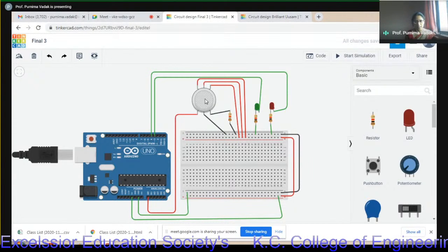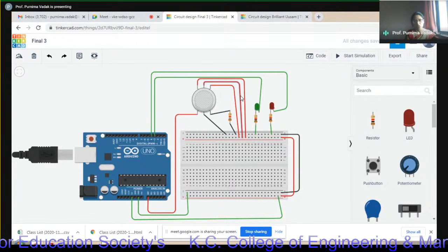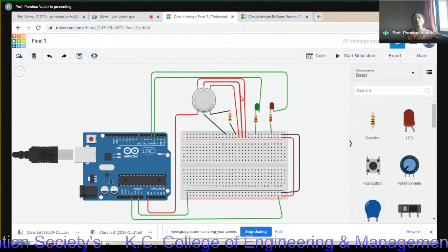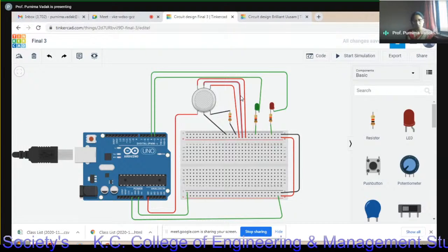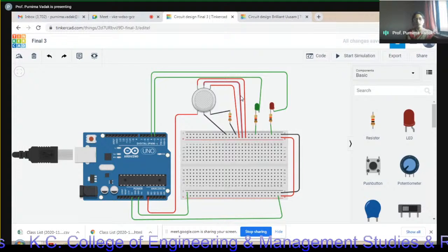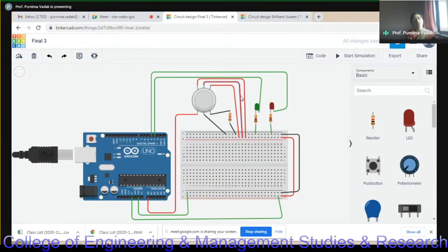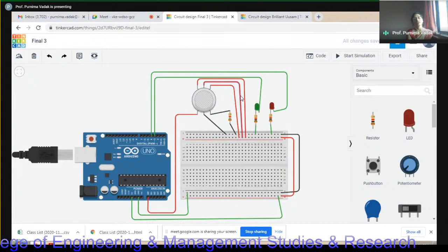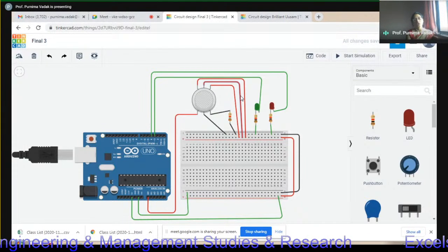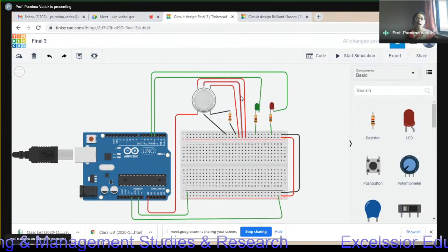Now, what is this gas sensor exactly? There are various sensors used for detection of gas. There are different sensors for different gases. Here, this sensor is used for detecting the LPG gas present nearby. What happens whenever a gas comes in contact with these sensors, the ionization process takes place. Due to the formation of ions, a potential difference is generated. And this potential difference is nothing but the output of the sensor. Now, if more gas is detected around the sensor, more potential difference is generated. In short, we get the idea about the gas detected around it with the help of the output value.